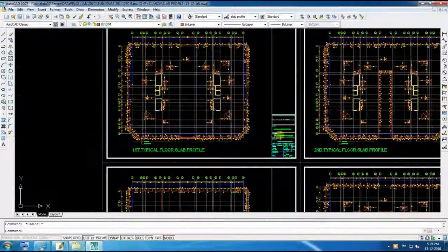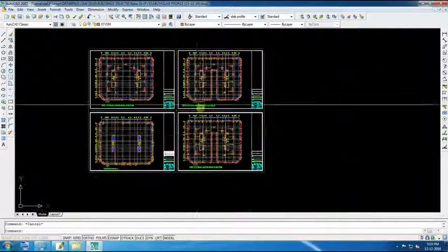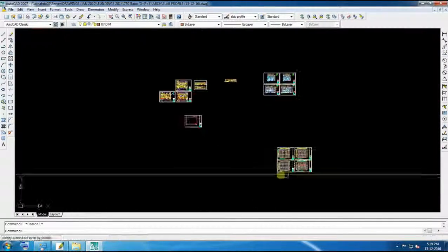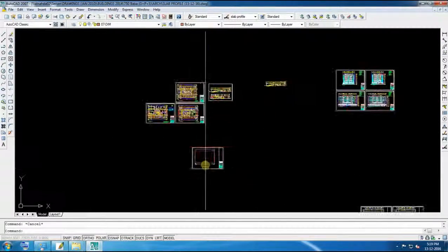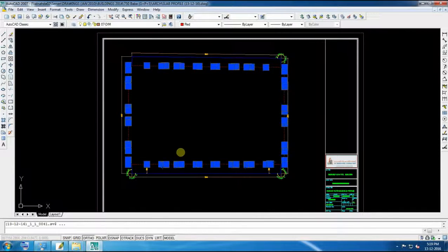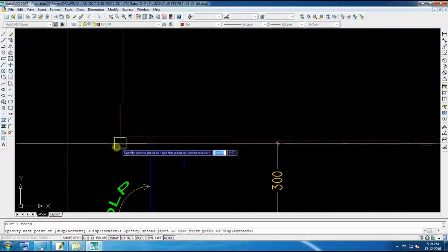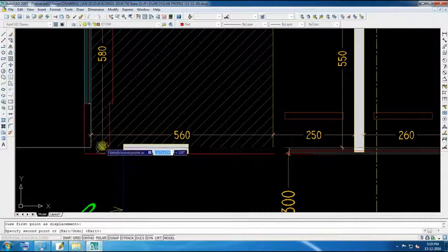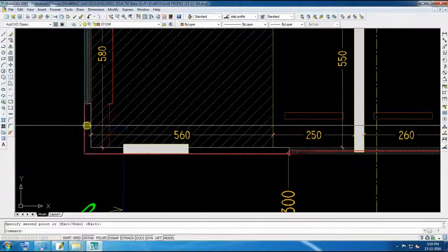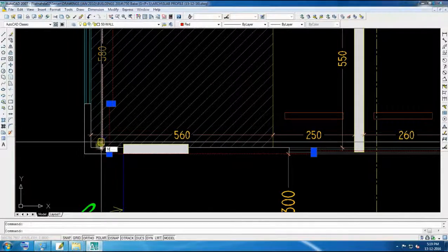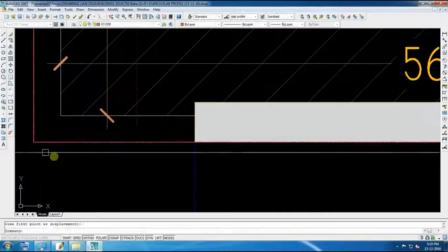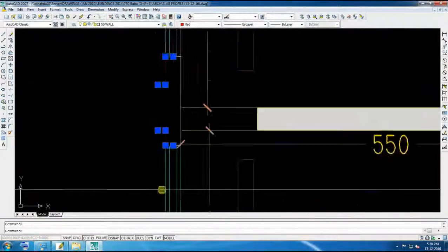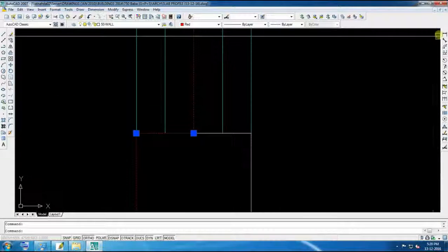So we will see how to make a slab profile for construction. Here, each step is very important because whatever we give here will go to site. I already made a polyline to save time. Wherever our glass is coming, we give it 10 cm inside, for fixing curtain or glass.